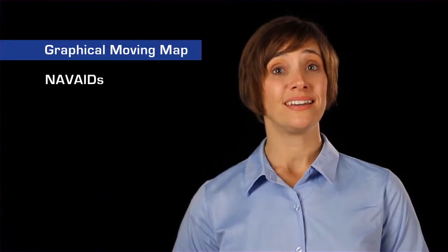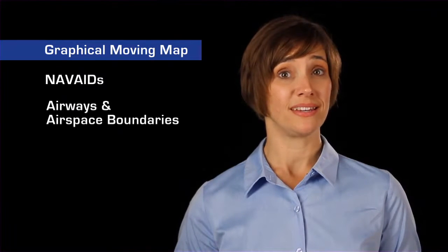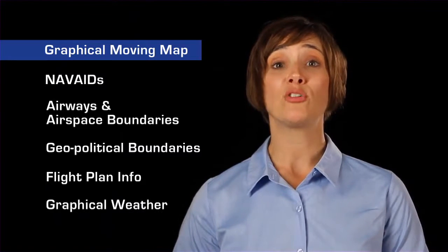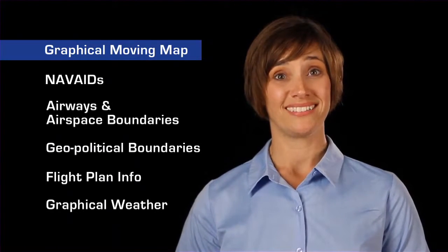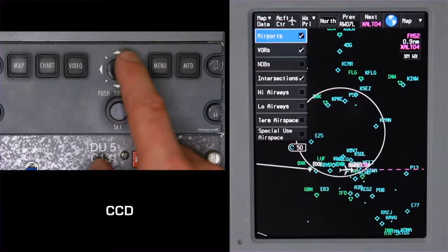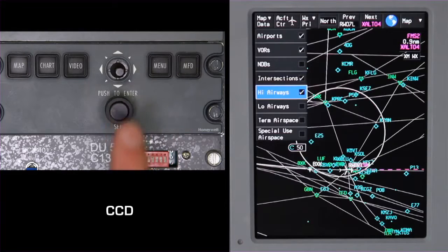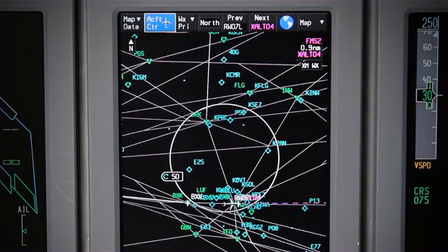The Primus Elite display system has the ability to display a graphical moving map. The map is capable of displaying nav aids, airways and airspace boundaries, geopolitical boundaries, flight plan information, uplink graphical weather, and much more. The pilot can choose the items to be displayed on the map using the CCD and various drop-down menus. The map display features a control bar that contains menu selections and drop-down menus that can be used to select the display characteristics of the map.